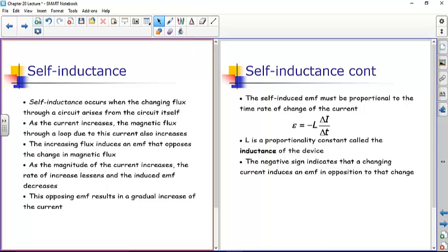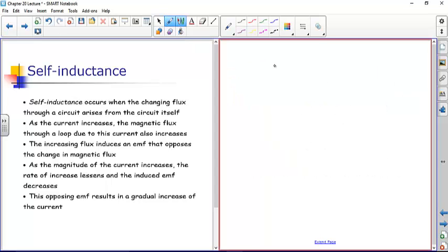So before we talk about that, I'm going to go through some scenarios here. We talked about capacitors, and we said if we hook up a capacitor to a battery, what would theoretically happen is, as soon as you close the switch, the capacitor would almost instantaneously become charged, because there's nothing to limit how quickly the charge gets redistributed around here.